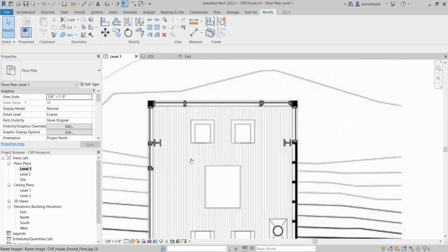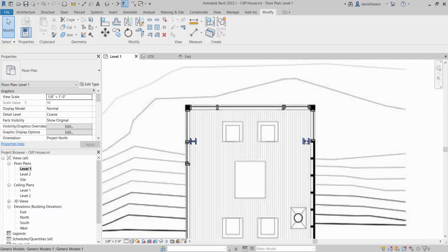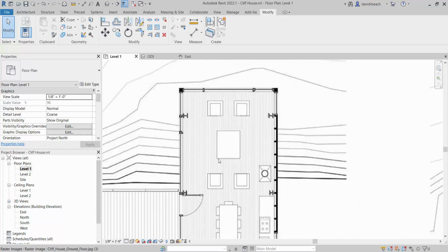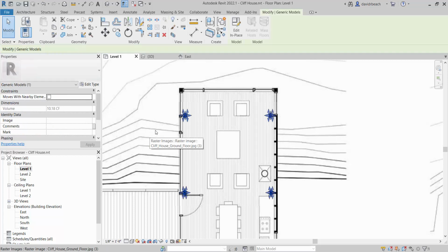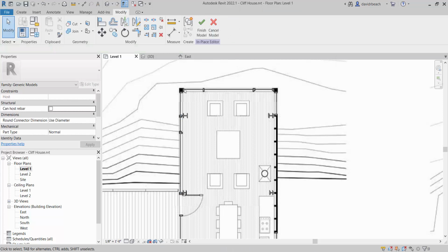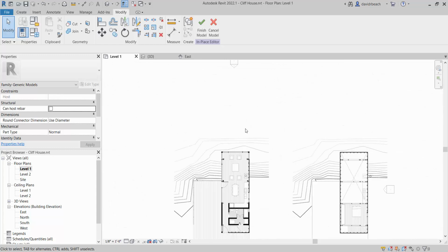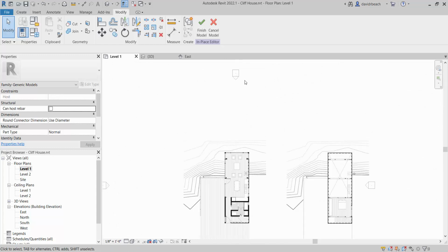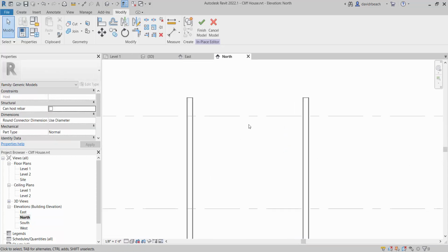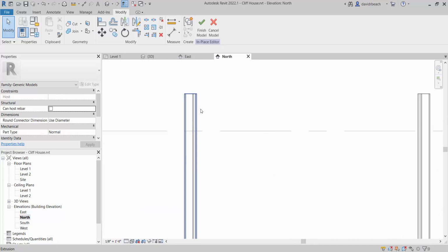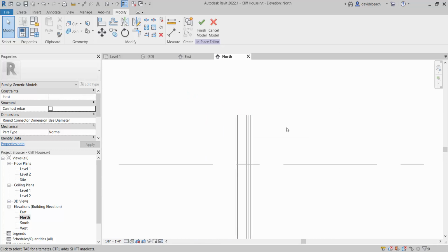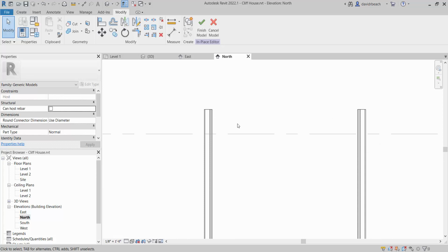Okay, so inside of Revit, I'm going to keep those beams running back in the same family as the columns that I already have. So I'm going to select those columns, and I'm going to go Edit in Place to open up that family. I know that I'm going to draw those from the north elevation, right? That's my north elevation right here. If I look north, I've got the two columns. If I change my view to wireframe, I can even see the smaller columns running in the background, right? Here and here, those are the smaller columns a little further back.